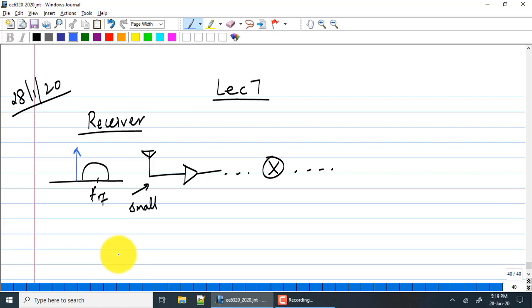The selectivity that you will need is anywhere from kilohertz to megahertz or maybe tens of megahertz nowadays. Okay, that still corresponds to a Q of several tens, which is very high. A Q of several tens is actually a very high Q system. In practical systems, you will see Qs of a few single digit numbers. That is probably the kind of effective Q of your receiver you will see. Okay.